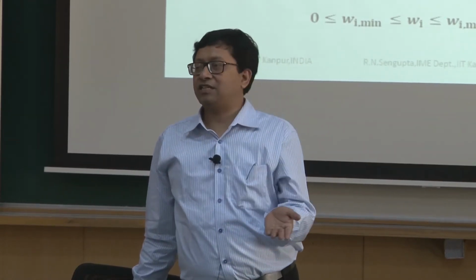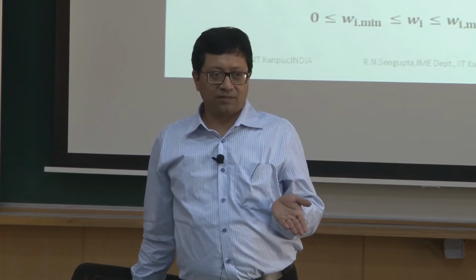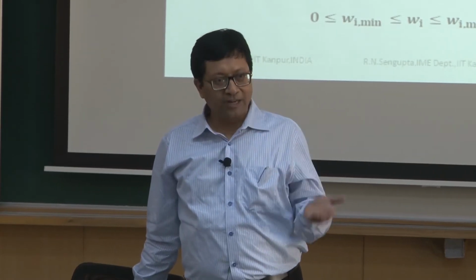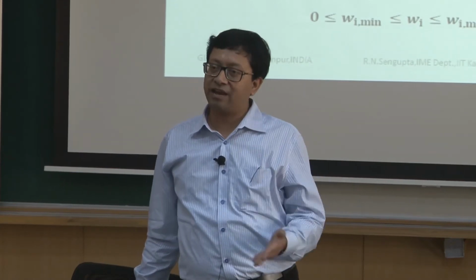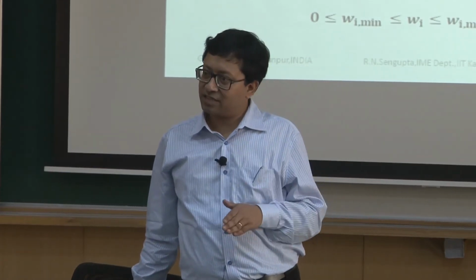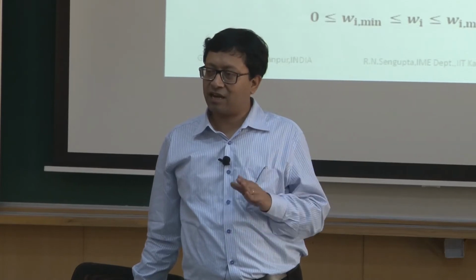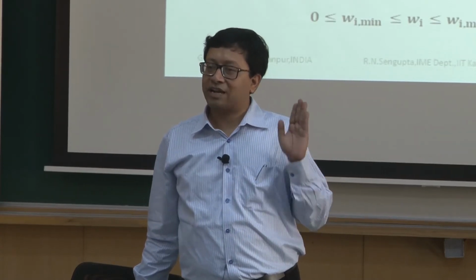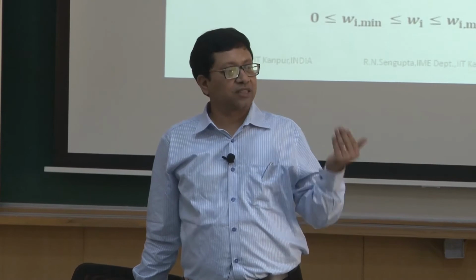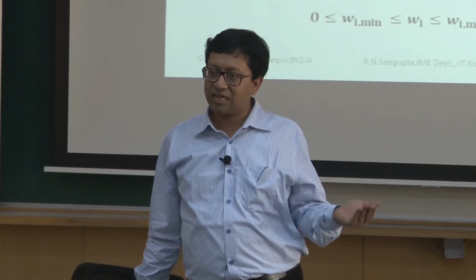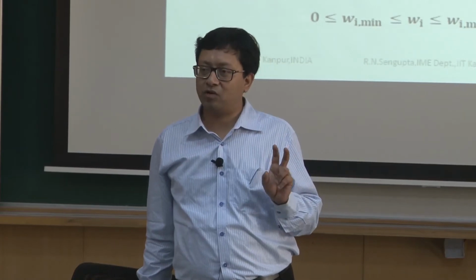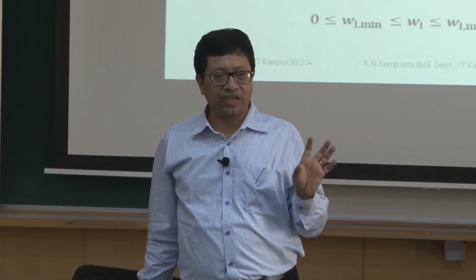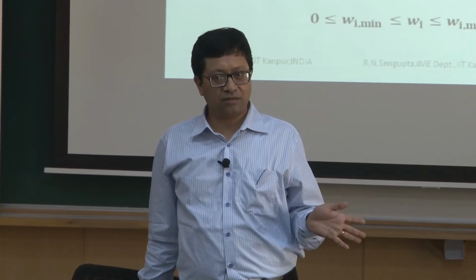Consider the scenario is changing, and a flood comes. The probability or the propensity of the flood breaching the dam is much higher in the second case than in the first case, when it is 118 rather than 120. So, the overall catastrophic loss which you will face in the second case would be much higher than in the first case, which means the total cost computed using the variance would not give you the right picture.